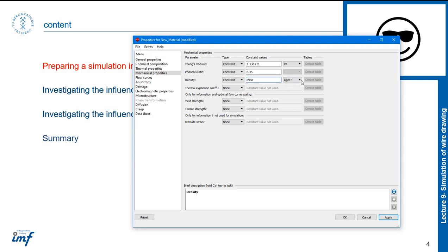You can see in this software you have the unit here and you can change the unit, but as I said last week, Abaqus is a unitless software, so you cannot see a unit in Abaqus. Then you should be careful about the units. The units should be coherent in your simulation. If not, your result will not be accurate.